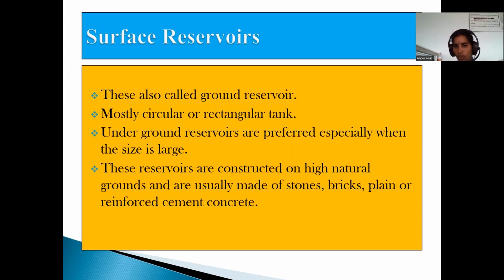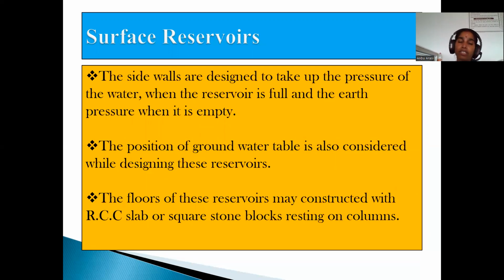These reservoirs are constructed on high natural grounds and are usually made of stones, bricks, plain or reinforced cement concrete. The side walls are designed to take up the pressure of the water when the reservoir is full and the earth pressure when it is empty.